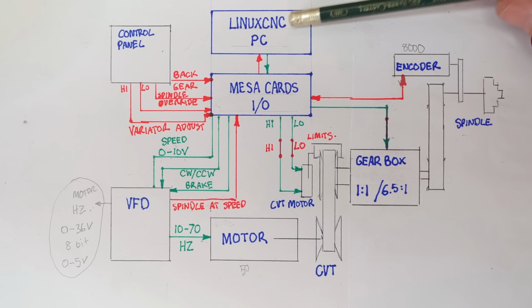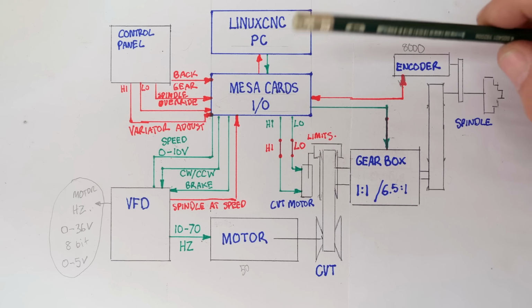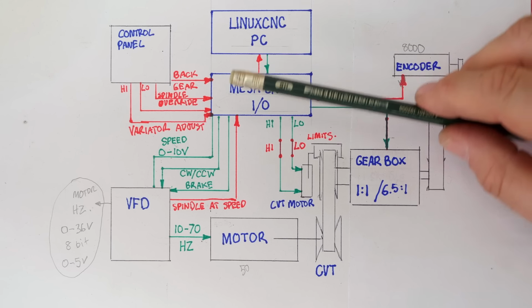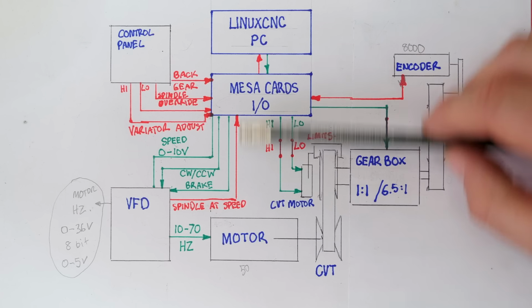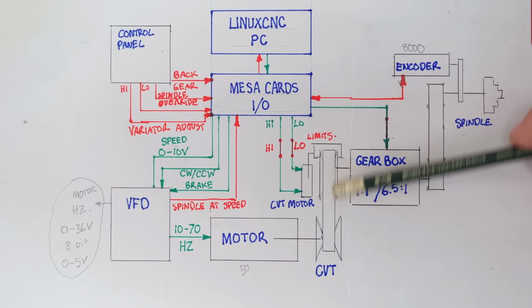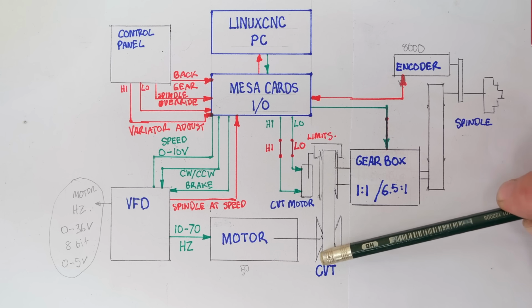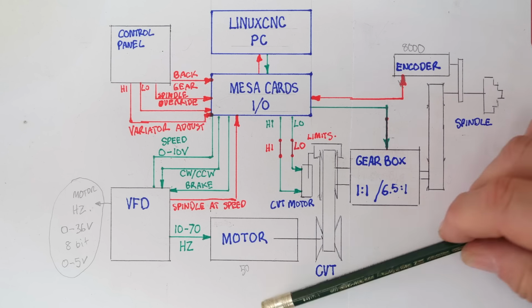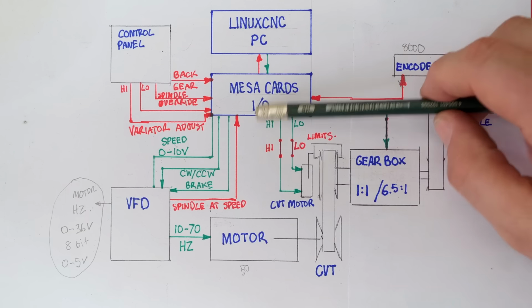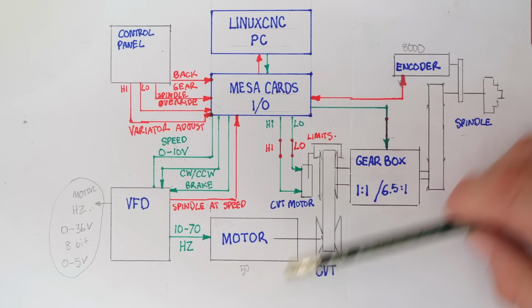To summarize the advice I've got, what I'm effectively trying to do is control two different feedback loops, one to the VFD and a slower one to the continuously variable transmission, but I've really only got one equation, and therefore I could only do one or the other and not both simultaneously.